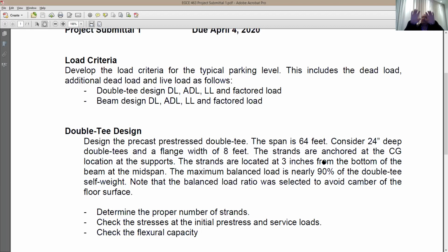And all of a sudden you see the double T's like this, goes up. And to avoid the deflection, because deflection is going to be an issue, you do it, let's say, to 90%. So with 90%, what you're saying is, I don't want to take it to 100%. Otherwise, I may end up with some camber. Also, I don't want to see loss of deflection. So I'd like to eliminate the effect of the deflection due to self-weight. This is the reason that you go here to 90%.